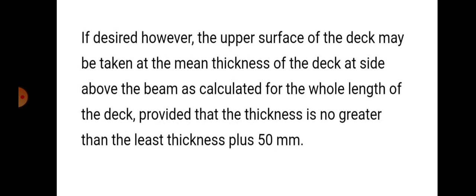If desired, however, the upper surface of the deck may be taken at the mean thickness of the deck at side above the beam as calculated for the whole length of the deck, provided that the thickness is no greater than the least thickness plus 50 mm.